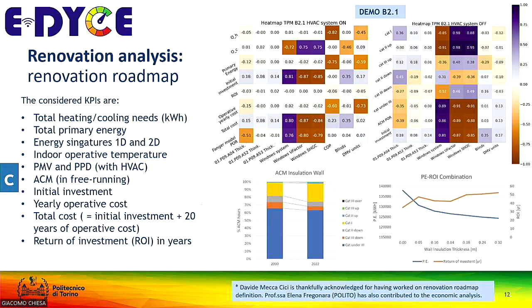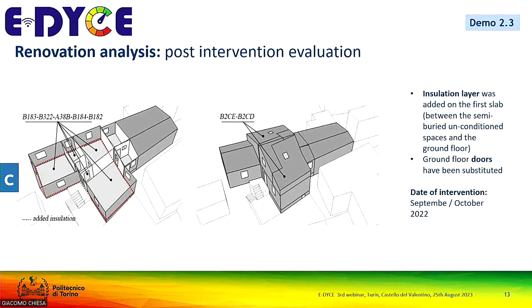That allows in some way to test the impact that a single action has, in percentage, on a large or customizable set of indicators: final energy, primary energy, thermal comfort, number of hours above a certain threshold, CO2 eventually, if you are able to simulate, like more in public buildings when you have a schedule of people. And that is useful to support, in a fast way, we can say, a potential orientation toward the choice of the correct scenario and reorienting it.